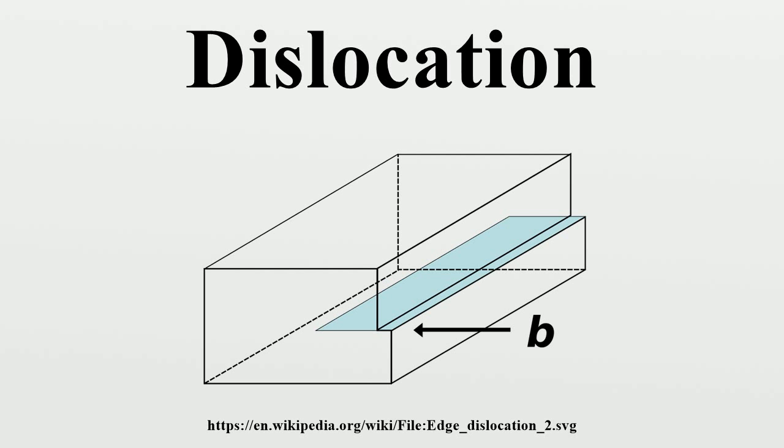After chemical etching, small pits are formed where the etching solution preferentially attacks the sample surface around the dislocations intercepting this surface, due to the more highly strained state of the material. Thus, the image features indicate points at which dislocations intercept the sample surface. In this way, dislocations in silicon, for example, can be observed indirectly using an interference microscope. Crystal orientation can be determined by the shape of the etch pits associated with the dislocations.